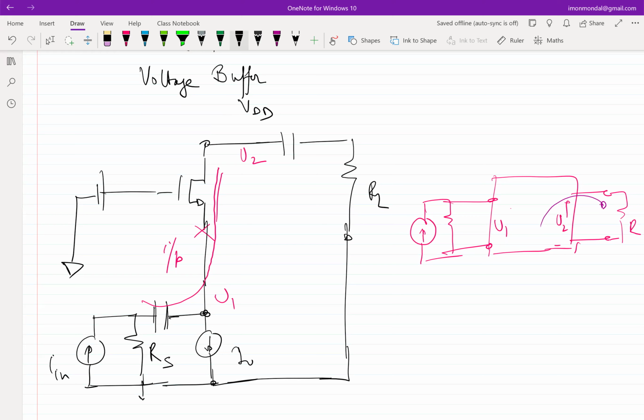But again, you see there is an issue, right? I mean, you cannot have very large values of resistances. If you have very large values of resistances, you have a problem, right? So as it turns out, in most of these architectures, you have to live with either putting a current source on the top, that is on the drain side, or on the source side. You cannot put two independent current sources on the drain and the source. Then you end up having those issues of having to satisfy the conditions of two current sources. So you need to have only one independent source.